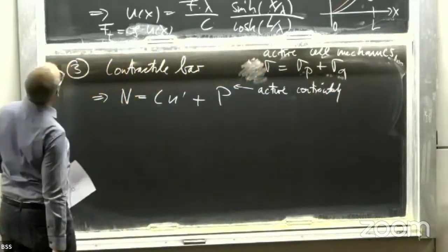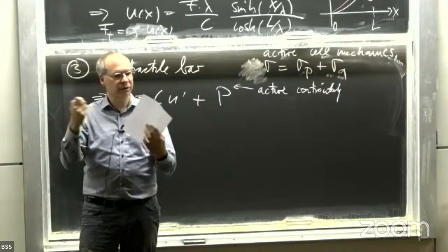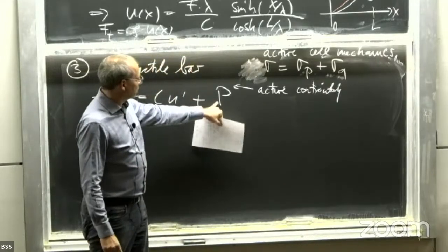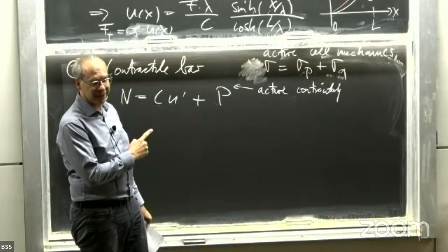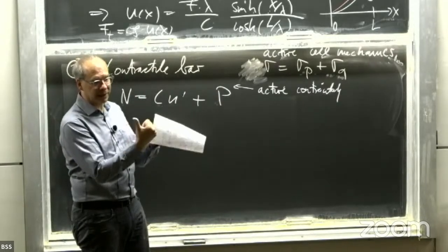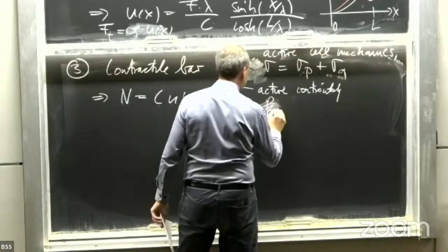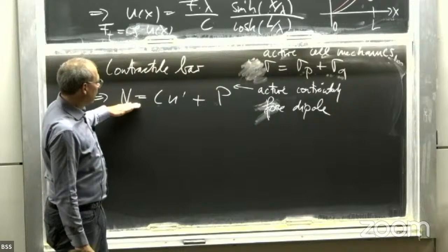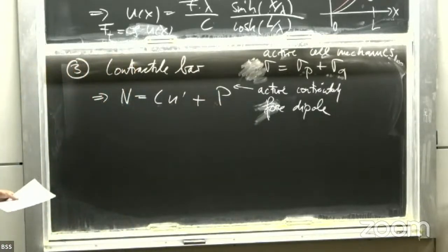So remember what I said when I started all of this, I said I have this slice. And if I say there's an internal force, I always say it's perpendicular to the normals, okay? In the force balance, it's actually two forces, right? Now I write here a new element P for the internal stress or force, and this again is two forces, okay? Because in continuum mechanics, you always have a little element which is pulled on all surface elements, and there are only two surface elements, and they're pulling against each other. So what we really have here is a force dipole. If it was a force monopole, you would not couple it here. You would basically couple it as a body force, but not in this way, okay? So this is really a force dipole if you do it this way.